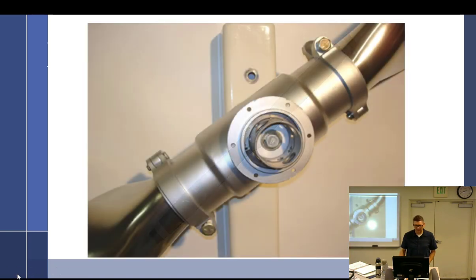Got that? Next, we have the ground adjustable propeller. The blade angles can be adjusted on the ground with proper tools. I suppose if you try hard enough, you could do it in the air. You have giant clamps right here, so three really. This counts as a clamp because it clamps the two hub halves together.